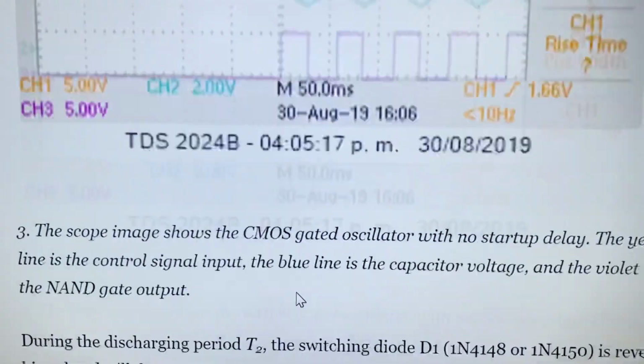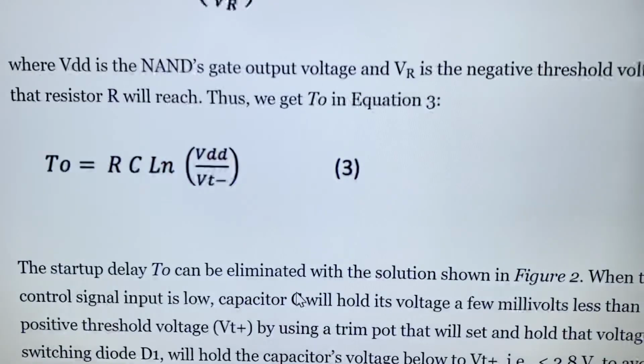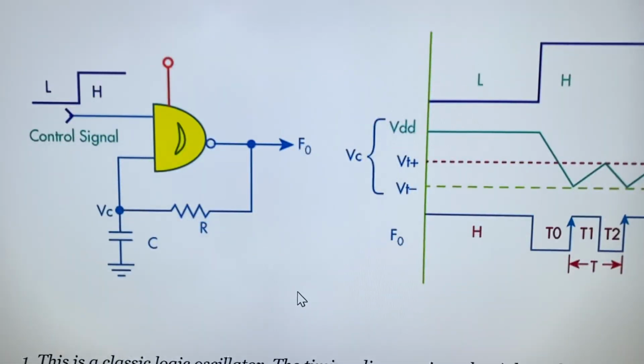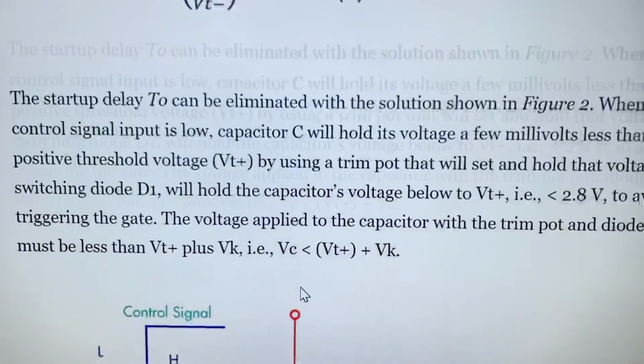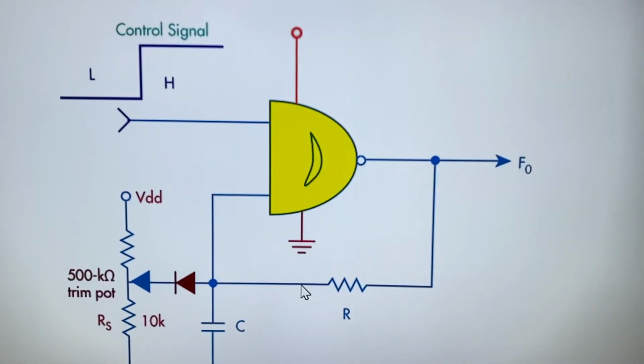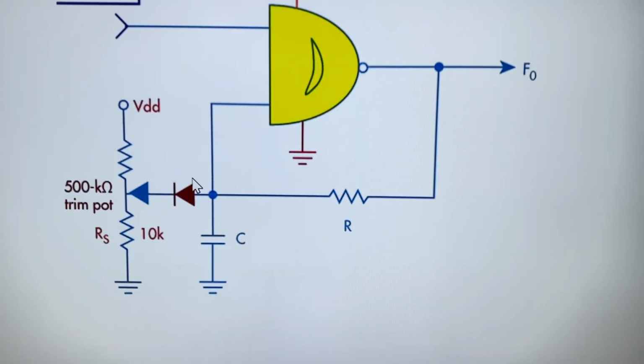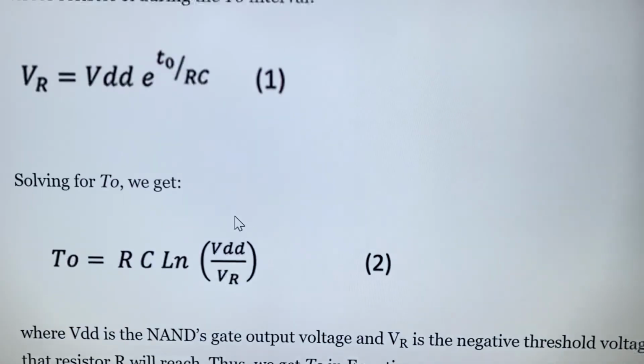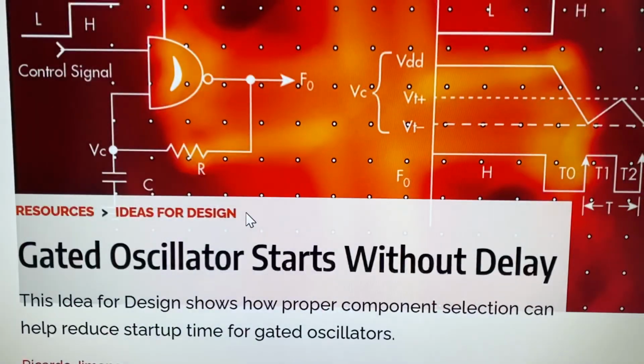And I want to say, as a final thing here, that once you are putting the diode here, there are diodes that have a voltage of 0.7, 0.6, but you can get a germanium diode with a voltage less than 0.3, 0.2 volts, okay, and that'll be even better to adjust it right here. So this is a brief summary of my article.